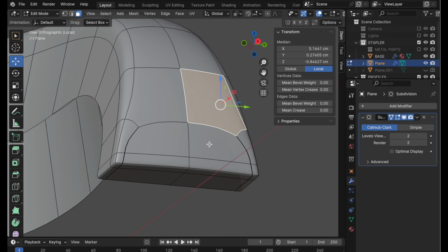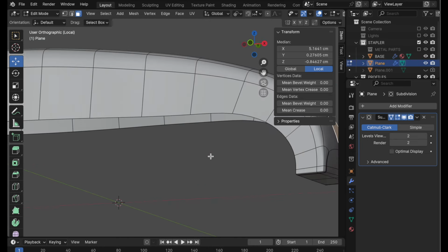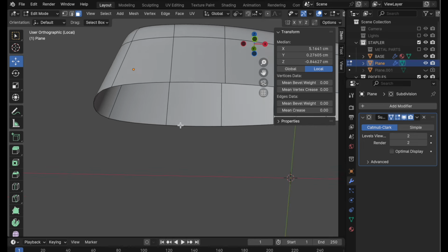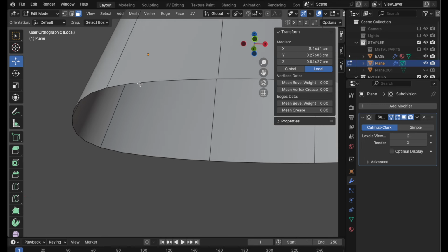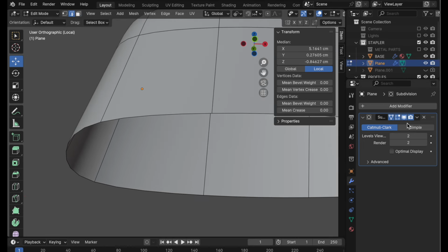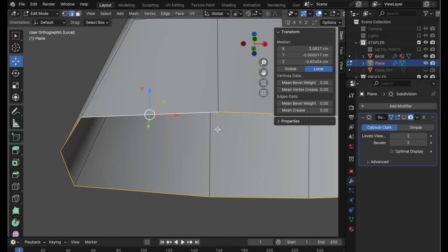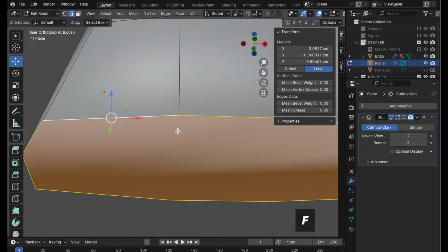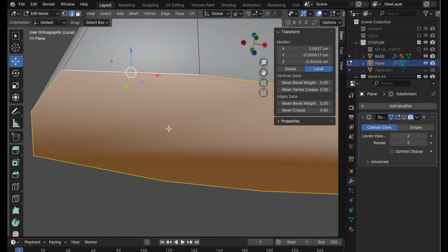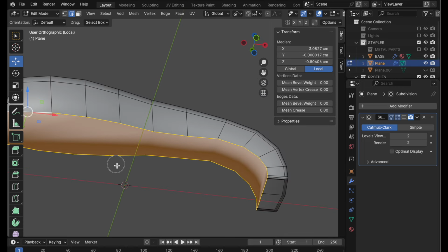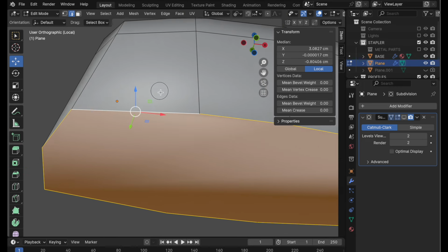Let's come in now, and we need to put a lip around the bottom, like a sort of border, so it's not just this hard edge. Come into edge mode. Let's go ahead and turn off subdivision and double click. Press the F key to fill that with the polygon. It's a big, gnarly ngon like that. That's okay.